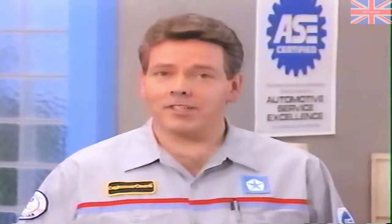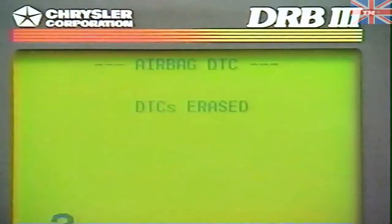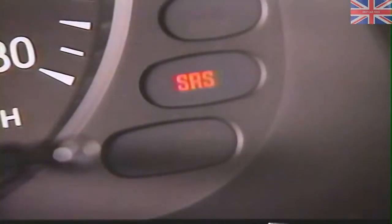Believe it or not, SRS diagnostic units are being replaced because diagnostic trouble codes are present, when these codes could simply be erased. If you erase the diagnostic trouble codes and the SRS warning light still does not go out, follow the procedures described earlier.